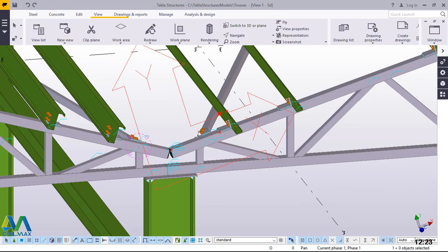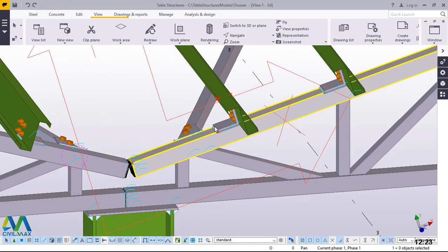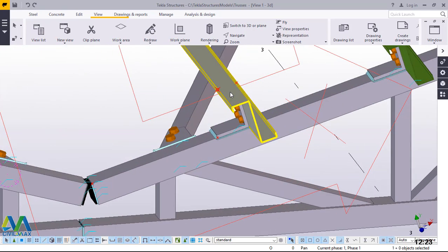Now what we're going to do, we want to create a plate of 3 millimeter thick, though it's so thick, but it's okay. When coming to actual work, we can change it to a 2 millimeter sheet and bend it to take the profile of a very good gutter that will be draining or directing the flow of water into the downspout, or from the downspout straight to reservoir for domestic use. Now,